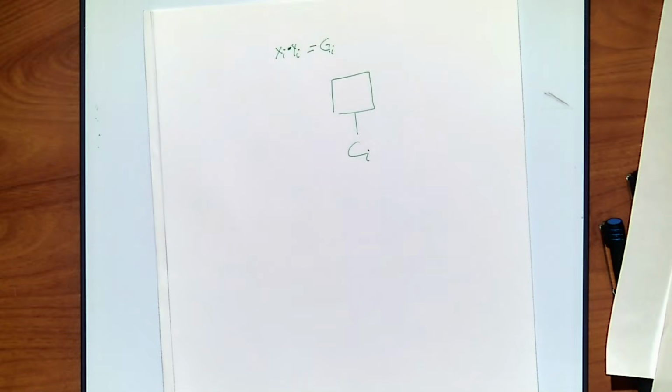Notice that especially for the first half of this, we added those 2 bits to generate the carry, and the exclusive or to generate the sum. We're just using that carry function. We can give it a new name, generate. It's guaranteed that if it's true, you will get a carry. So we call it generate, and we can compute it in parallel.